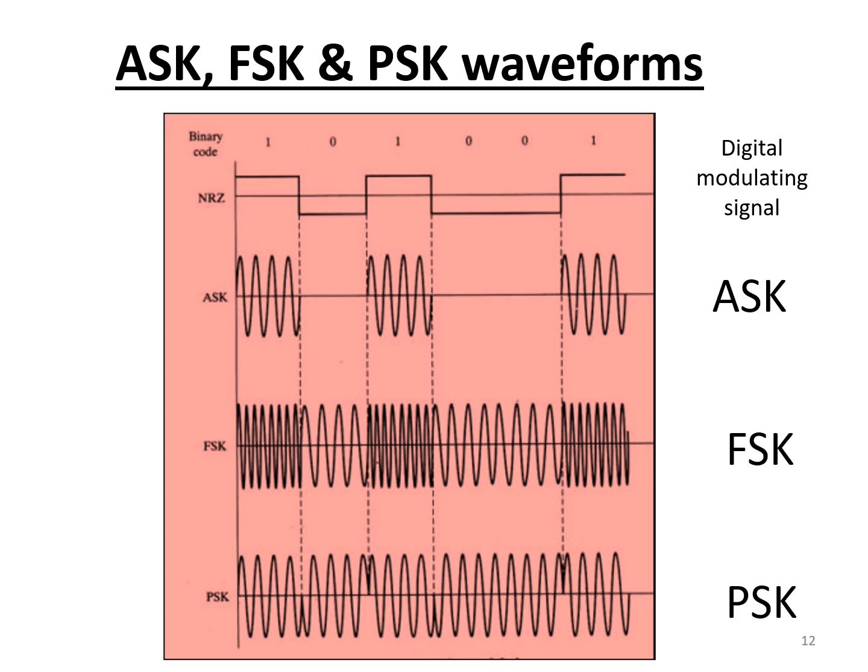In the FSK technique, the frequency of the carrier will be higher for logic 1 and lower for logic 0. Based on this PSK waveform, the phase of the carrier is shifted by 180 degrees when the binary level of the modulating signal changes from 1 to 0 or from 0 to 1.